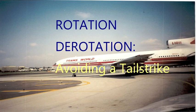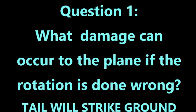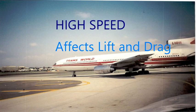The challenge here is to have the right amount of pitch, angle of attack, and rotation so that when it takes off nose up, the back of the plane doesn't hit the ground, so you don't have a tail strike. That's number 1. Number 2 is angle of attack, which is a protection against stalling the plane. Number 3 is bank angle, and that's also protection against stalling the plane, or a fast descent, which can happen with a bank angle. I'll explain a little more about what's involved with these different aspects or parameters. But you also have high speed.